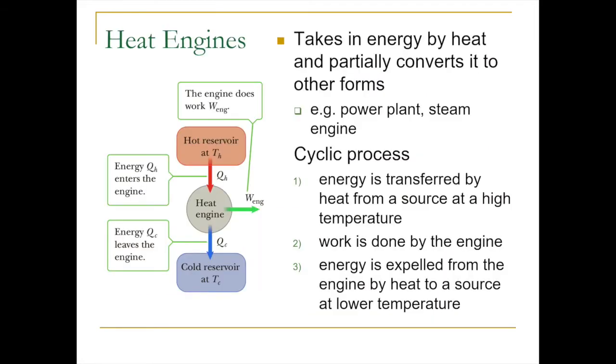If you take a look at the diagram, you can see that we start off with this hot reservoir. If you remember, when we refer to a reservoir, we mean something that has such a high heat capacity and is so large that its interaction with the engine does not effectively change the temperature. The heat will then flow from the hot element to the engine, and once it's inside the engine, it's going to produce whatever work the engine's required. And then the exhaust of this engine is going to go out to a cold reservoir, and in that process it will be condensed, or whatever needs to be done in order to start the process again.